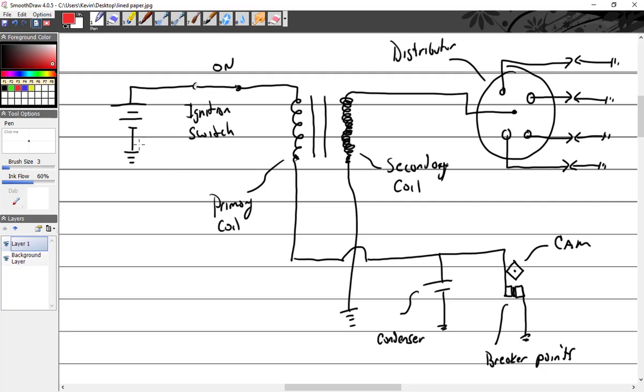We're going to use, okay, this is a good example of why it's easier to use conventional theory than electron. Because with electron, I got to start here, and I got to find where I want to come up. But here, I can just draw through, because the line's already there. And I can say it goes through the switch, and it goes through the primary coil. Does any current flow through the core? Okay, this is the soft iron core right here. It's a transformer. Any current flowing through there? No. All right, so all we have is current flowing through here.